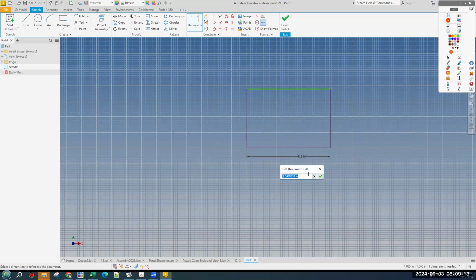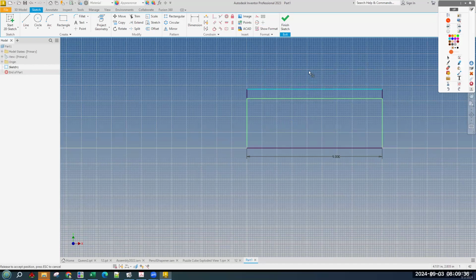Just like a tool, you should get the pop-up, and you can just press, oh no, wait, it's 9 wide. Hit enter. Okay, you see it changed the shape. It also changed the color of these because they are now constrained. If you were to click and drag these black lines, you can't change their place. You can still change this, and that's because nothing vertically is constrained.